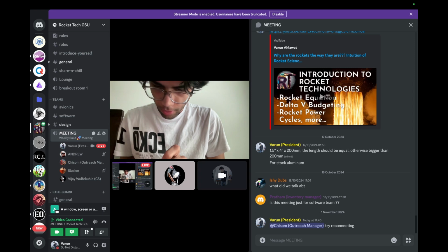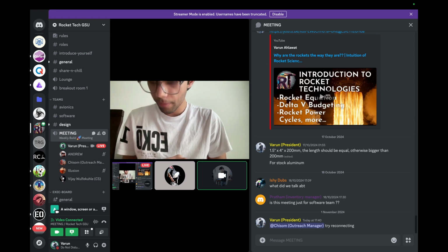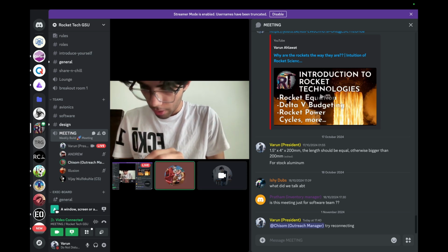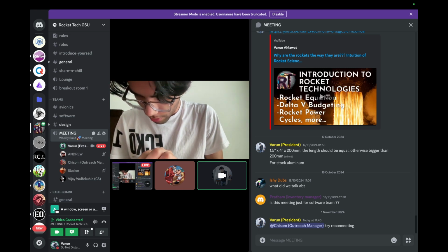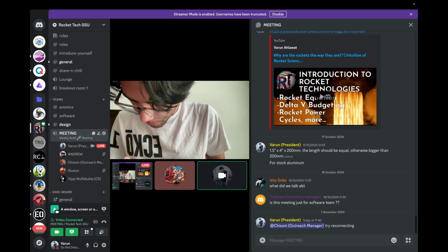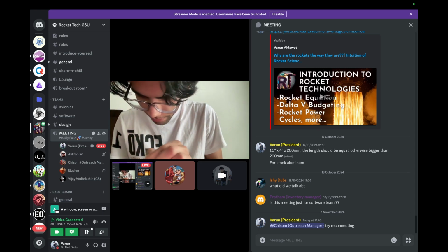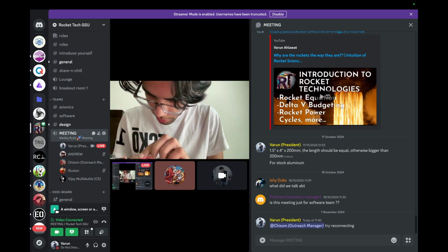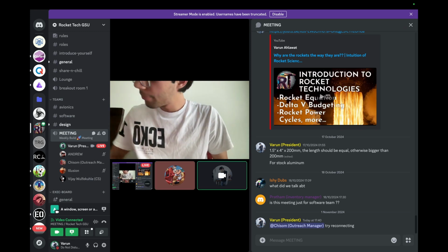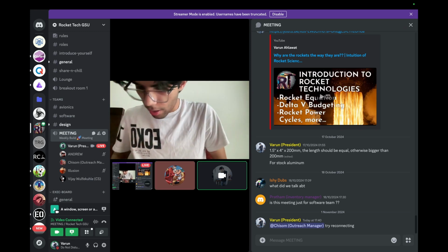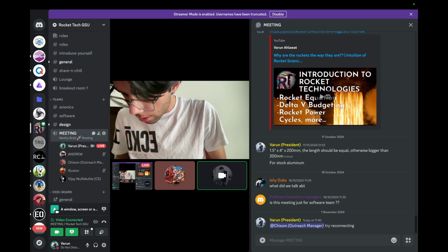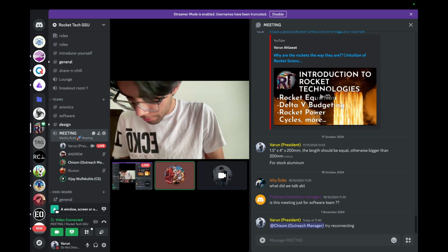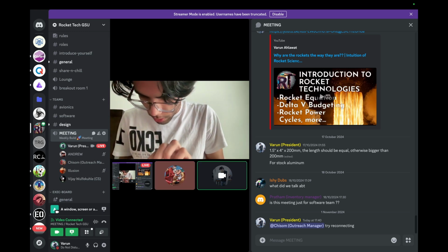And then the second after that, what pin was it? Y out. Y out, yeah. Okay, I've connected Y out using the blue wire onto... wait, I cannot use this one. I cannot use this one either. On G19. G19? Yeah. And the only remaining one is the X one, right? X out. Yeah. I'm connecting that to G18.